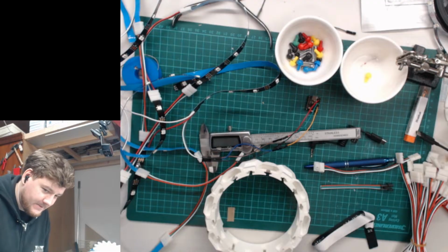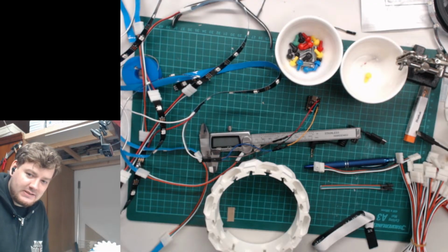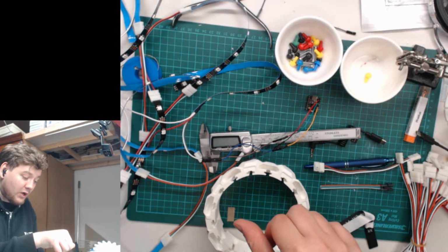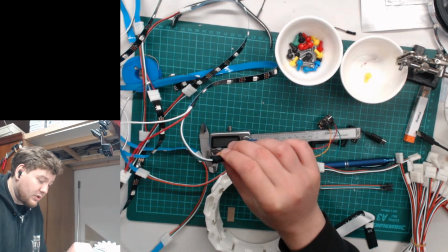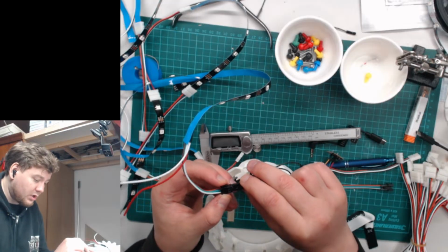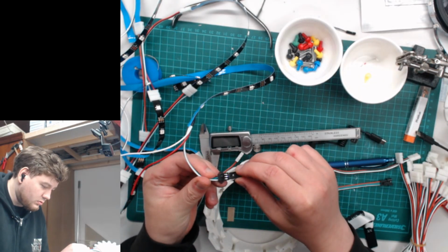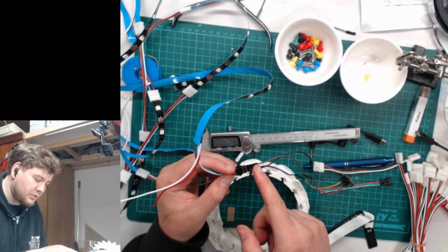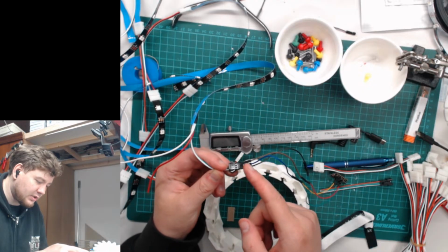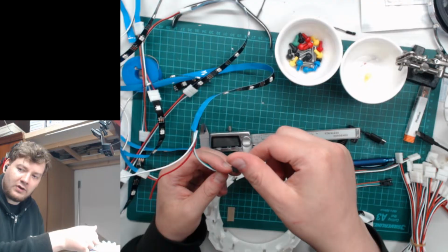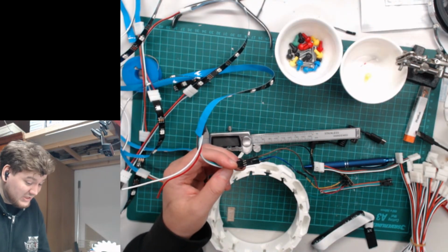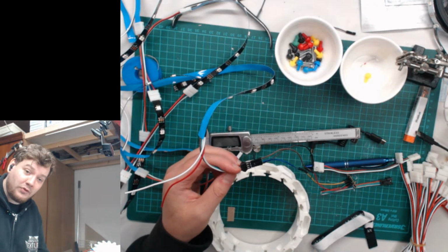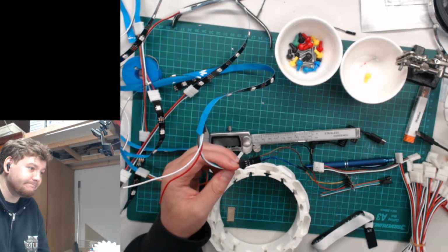We wanted something a little bit safer than just 3 pins, because the 3 pins work, but they can get loose. People can flip them around by accident, and the other one is one-sided in direction, so maybe we can duplicate the plug. Maybe. You know what? Maybe we can make a special pin on the PCB that has the clicking side on one side, so you cannot flip it around by accident. Because this is not USB-C, it needs this side in, not that side in, because then you're turning your ground and your voltage around, and then all the LEDs say boom. Yep, there's the smoke.